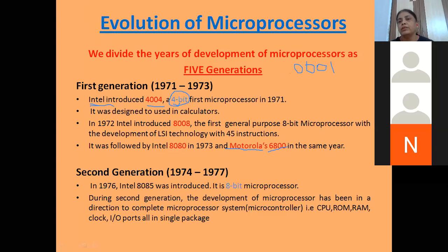This is one of your combinations. It is 4-bit because all are in binary; bit means binary digit. If I want to write 3, the combination is 0, 0, 1, 1. That is your 3. Understood? This way we can have 16 words, or 16 instructions we can give to this microprocessor.